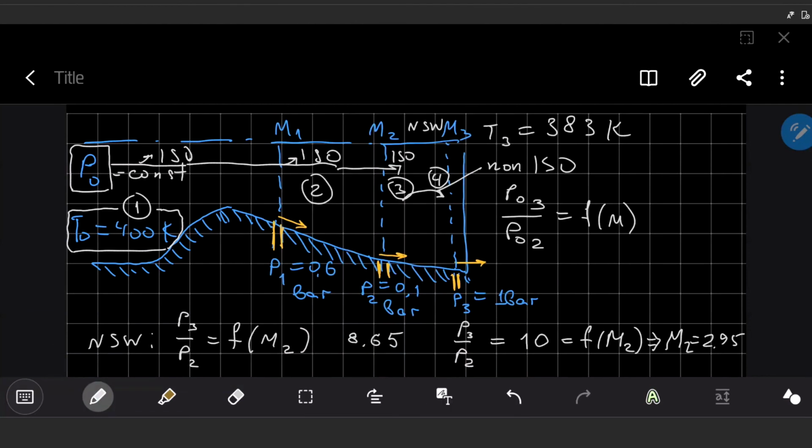You will see in the Anderson book something like this, a straight line, right? A straight line. But in the real application, we have interaction of this shock wave with the boundary layer, and we see a lambda shape, a shock wave which is facing the boundary layer from one side and from another side. I just try to draw this shock wave more realistically than it is in the book. Just more realistic.